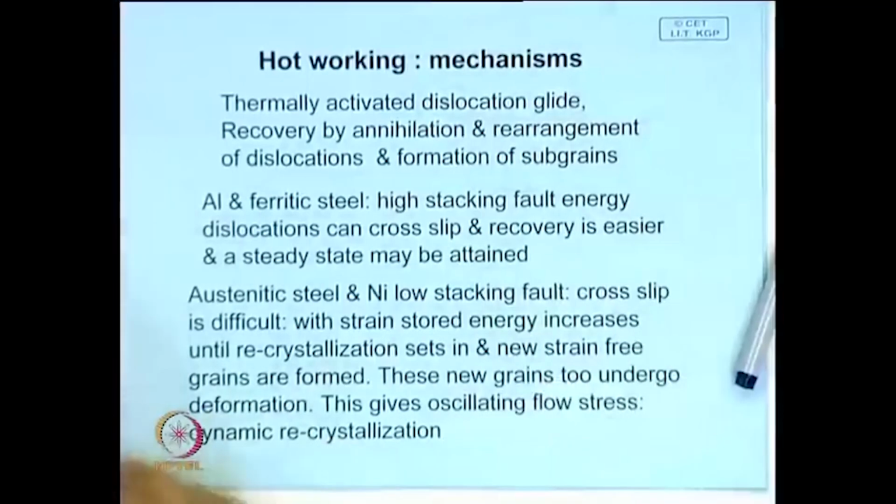Now, hot working is a thermally activated process, and here, when you deform, there is slip taking place, and for the slip to take place, dislocation movement is necessary. Dislocations are generated, but when this process takes place at high temperature, as dislocations are generated, there is also a parallel process of dislocation annihilation, because dislocations get some added movement; a dislocation can climb, and then they can rearrange themselves and try to occupy the minimum state of energy.